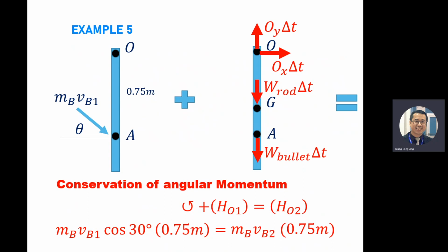Same with the after, right? After, mv multiplied by the distance. So for the left-hand side and right-hand side, you refer to the diagram over here. So you have this one multiplied by the length, m r multiplied by this one, and I_G omega 2. Again, this is the rigid body chapter. Your rigid body will have a second moment of inertia effect, so you need to include I omega there. Then you solve for the unknown.